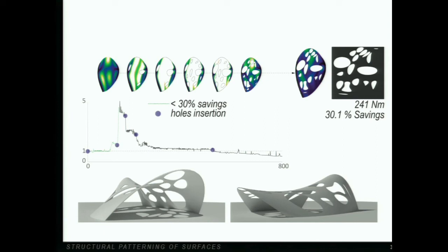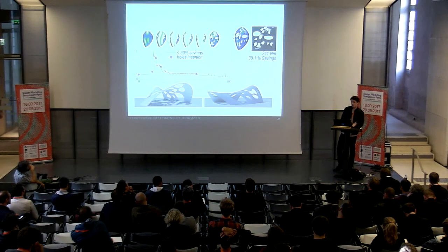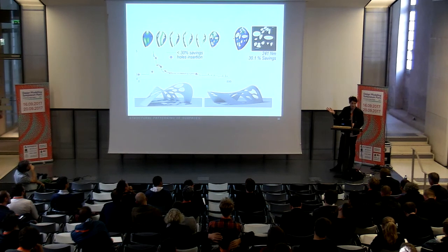Here we use the evotop workflow. The starting condition is the solid unpatterned configuration. Successively, holes, completely arbitrarily with random shapes, are added and subsequently optimized. First, introducing holes greatly increases the compliance of the structure. As the optimizer slightly modifies the shape and location, the stiffness improves. The example shows the usefulness of evotop to handle completely arbitrary designs and integrate any possible design intent. In particular, even with arbitrarily drawn apertures like this that don't really make sense, the system was able to find a solution performing better than the solid one.